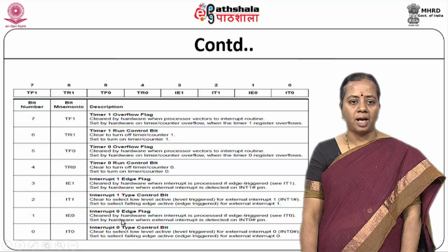And IE0, IT0, IE1 and IT1 are the 4 bits which help in external interrupts. The edge triggered mode is enabled by setting IT0 and IT1 to 1, for edge triggered interrupts.